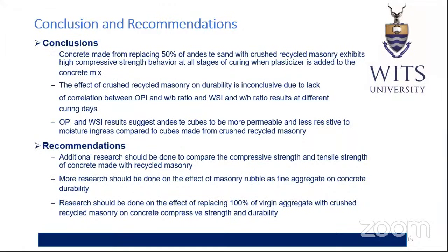The effect of crushed recycled masonry on durability is inconclusive due to lack of correlation between the OPI and water to binder ratio, and the WSI and water to binder ratio results at different curing days. OPI and WSI results suggest andesite cubes to be more permeable and less resistant to moisture ingress compared to cubes made from crushed recycled masonry.